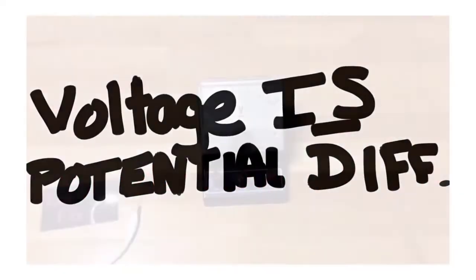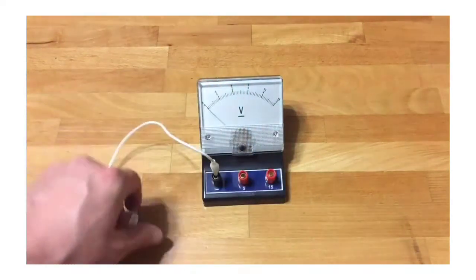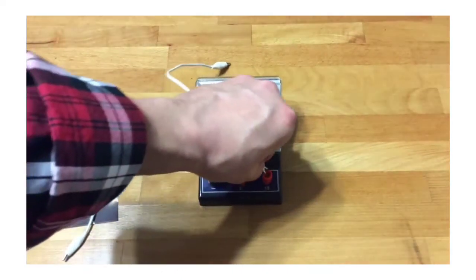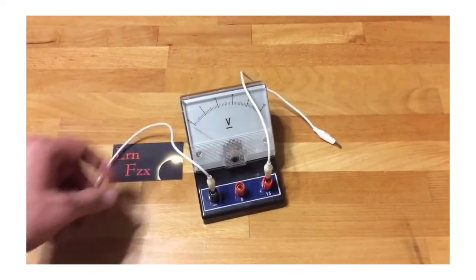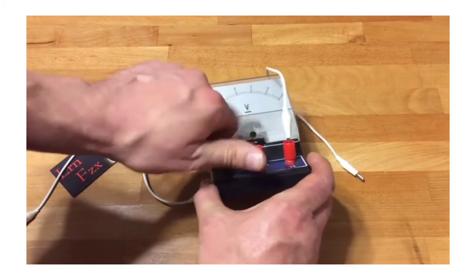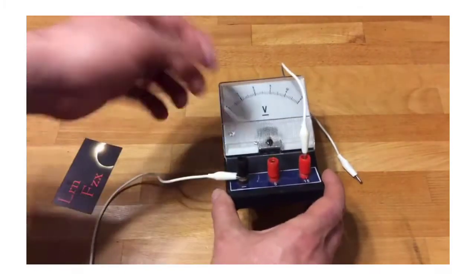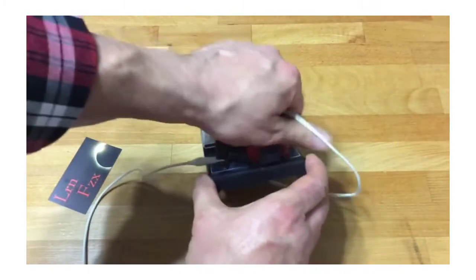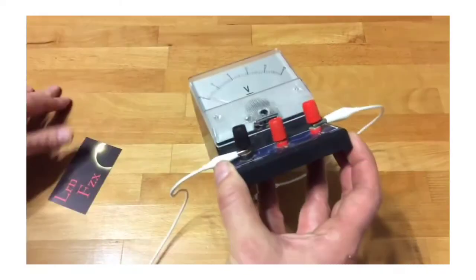The voltmeter requires two leads. One is positive, one is negative. The negative always goes to the black, and there are two possibilities for the positive. One has a maximum range of 15 volts, that's the one you generally start with. The other has a maximum range of 5 volts, which, if the reading is below 5, you can move down to. There are two different ways to connect it, either through the top or on the side.